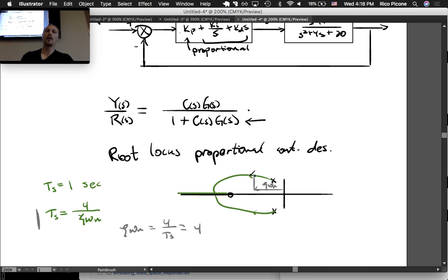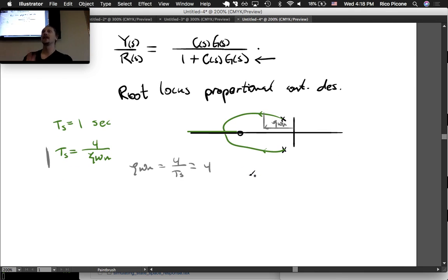So we know we want to add an integrator in because integrators, if you've gone through that argument before, if you add an integrator into your controller, it's going to reduce steady state error. If it's a finite steady state error and you add an integrator in, you're going to get 0 steady state error. Okay, so that's good. That's good for a step input. So we know, okay, we want 0 steady state error. That would be ideal. Let's put an integrator in there and see if we can make it happen.